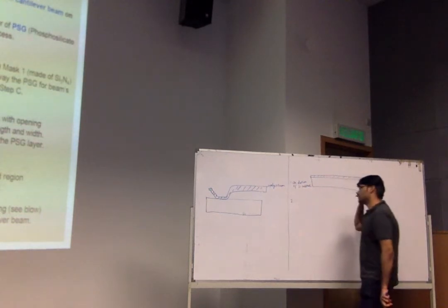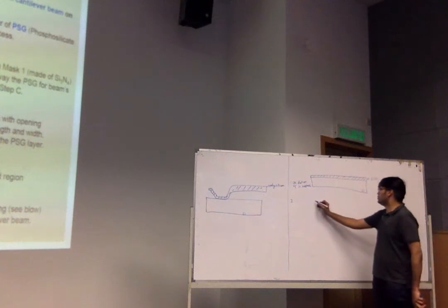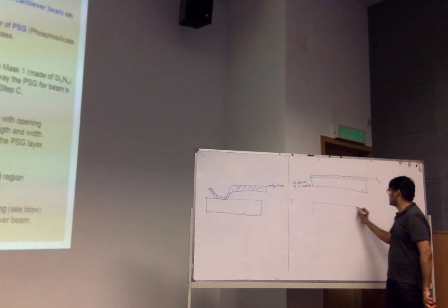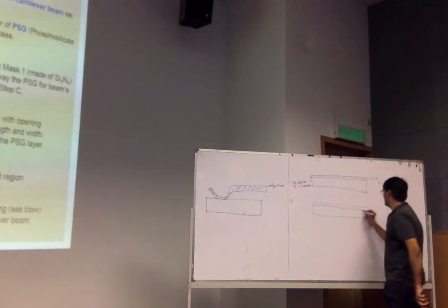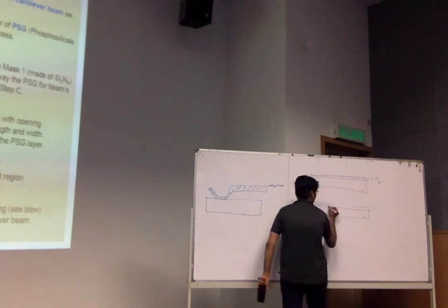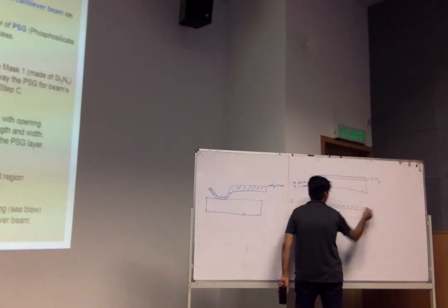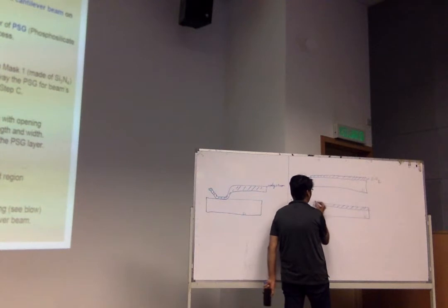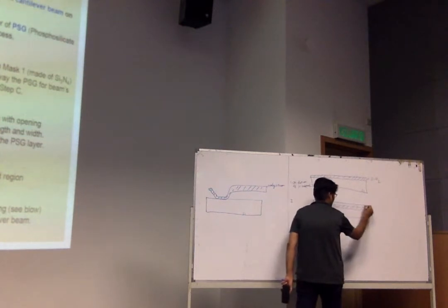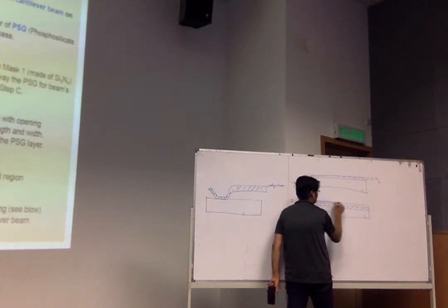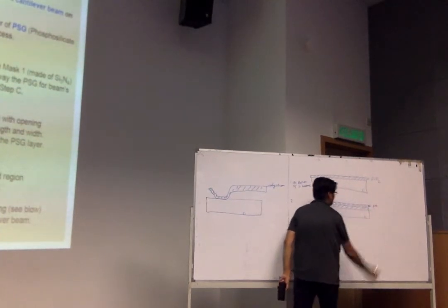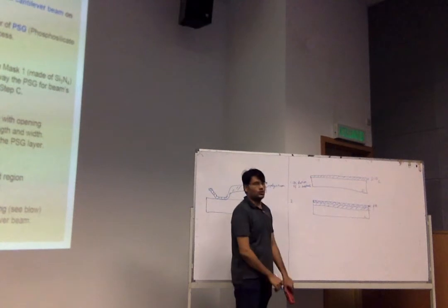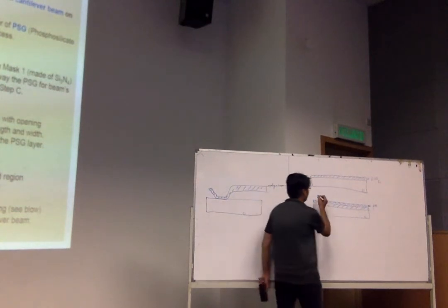Now the second step is to do a photolithography to achieve this step. What we will do next is use the same silicon over which we have the silicon dioxide layer, above which we should now make a photoresist coating. Photoresist. Then we should take a mask that contains